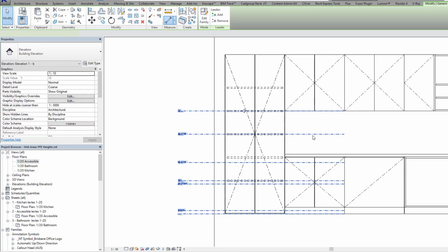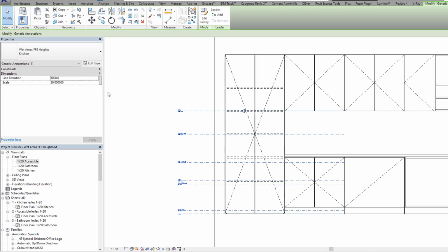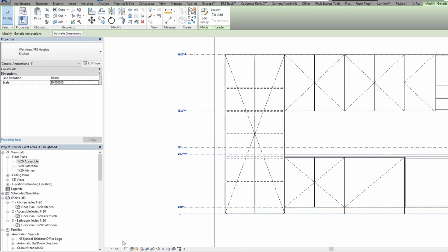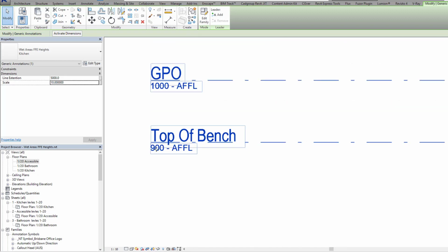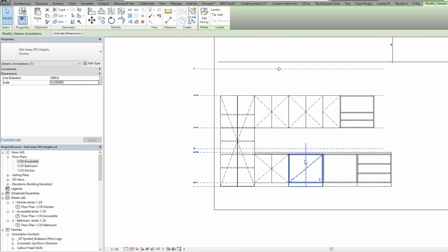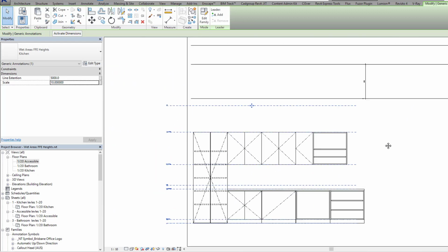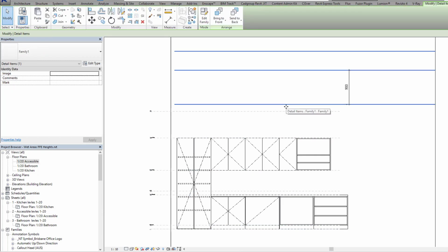And so to fix that, what we've done is we've built in a parameter in the family where you put in the scale that the actual view's on. So if I put 1 to 10, which this scales of 1 to 10, it'll then correct the spacing of all of these to still be appropriate, and it'll update the actual numbers to make sure that they still reflect what in reality you want it represented as. So that's the kind of workaround for that.